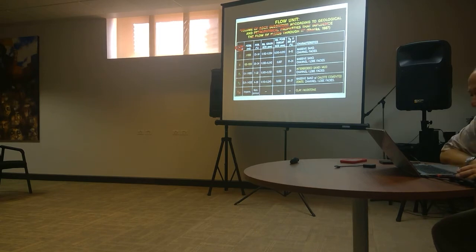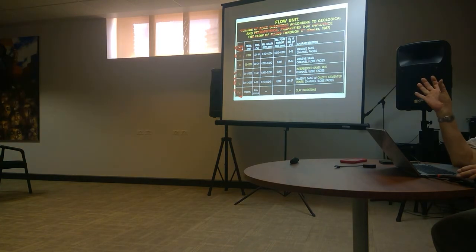I called this one E for excellent, G for good, PI for poor, and the I stood for interbedded, P sub C, poor, cemented, C for cemented, and P sub M, poor because you had a lot of matrix in the rock. And then I classified the permeabilities and broke out the units.